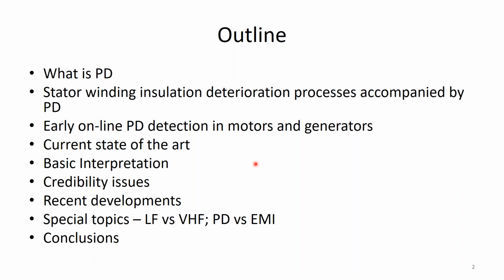I'll then talk about way back in the beginnings of time when PD testing was first introduced for motors and generators by Westinghouse, talk a little bit about the state of the art, and a lot of that involves dealing with the issue of noise. When we're talking about online detection, that's PD detection during normal operation, we're talking about when the machine is connected